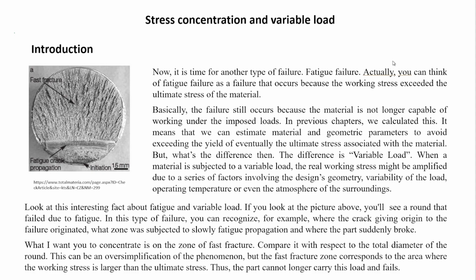Now, in this slide, you have a picture there, and it's a shaft, and this is a typical fatigue failure. You're going to see two big areas. You're going to just draw this line. This is this green line here, the one on the bottom. This one here is one part of the fatigue failure, and this is the other part, represented by the rest of the part here.